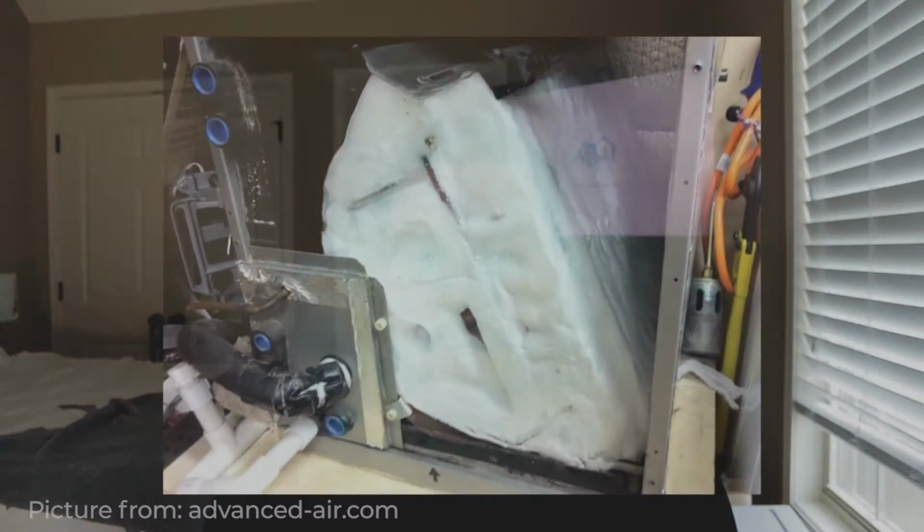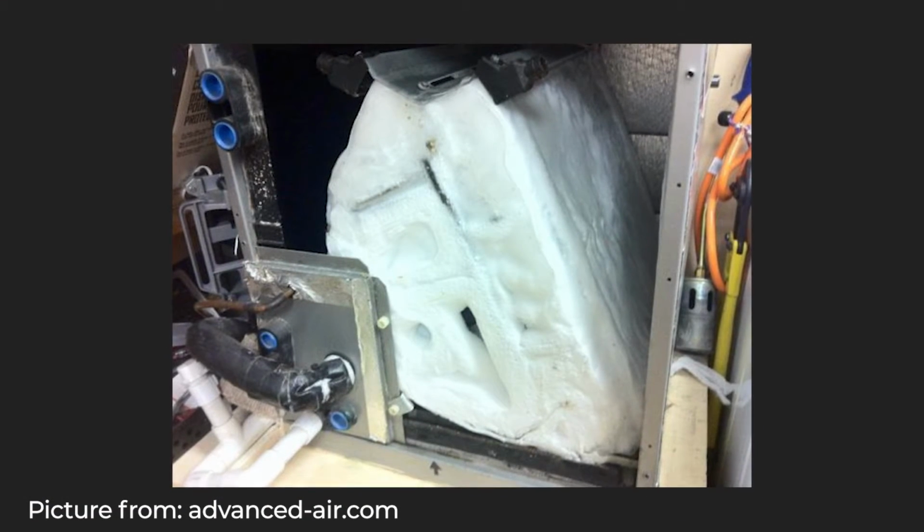So typically what this is going to look like from a problem perspective is that the evaporator coils are going to freeze up because there's not enough airflow to carry that cold air out and into the house. So you typically would start seeing your cooling capacity start to drop. You'd notice that the airflow off of your vents is going to start getting less and less powerful, and less cold air is being transferred in. So if you open up your evaporator coil and it looks like the back of a freezer, then you know that you've got a problem there.